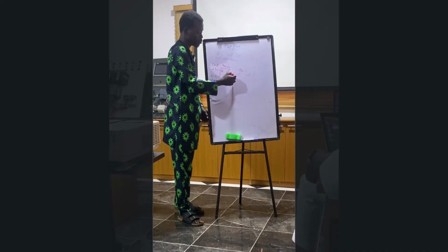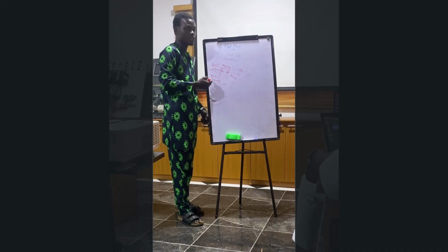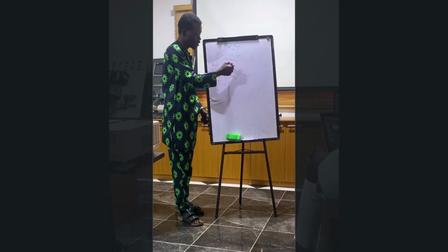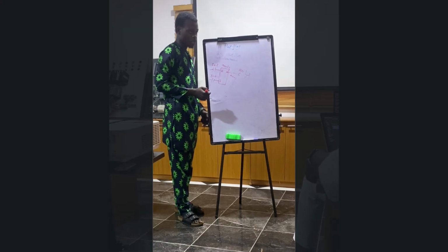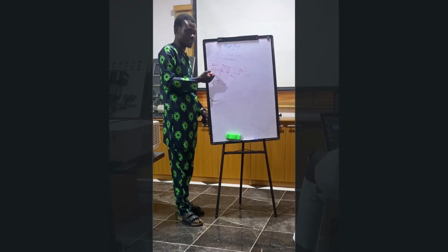0. Your RLO at this point will be 0. Okay? And it will remain that way until you press on the what? Set. So when you press on set, your RLO becomes what? 1. Okay? And then it will remain in that state until the reset is pressed again.